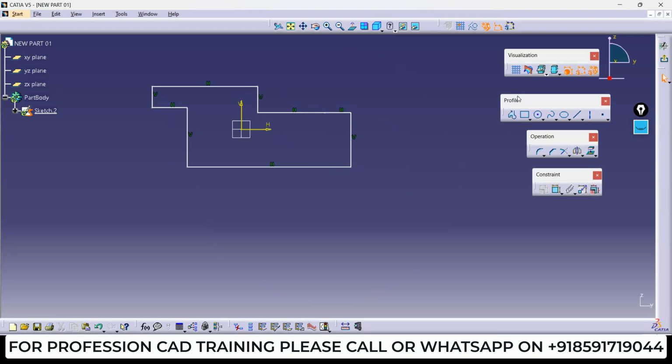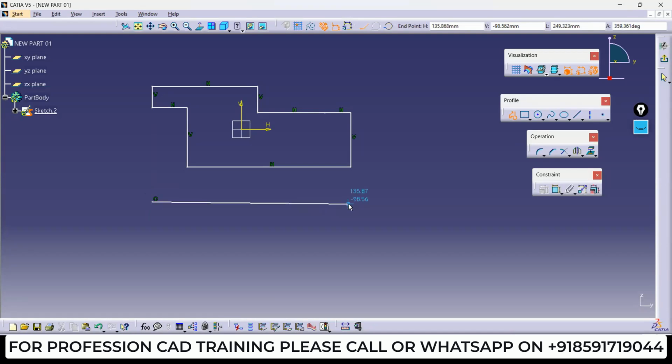So profile command, this is in the profile, first command is profile. The profile command is a continuation of the line and arc. Line and arc means you can create the sketch using line and arc in a single command. So if I create one line like this, you can keep it properly horizontal also. It will automatically take properly horizontal. It is turning blue, which means it is horizontal.